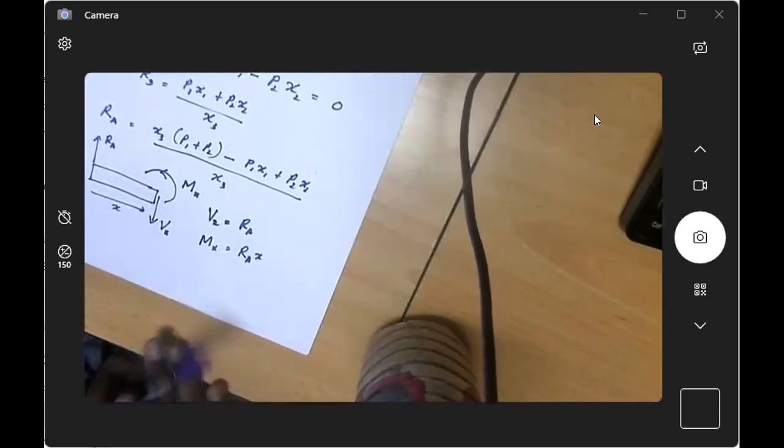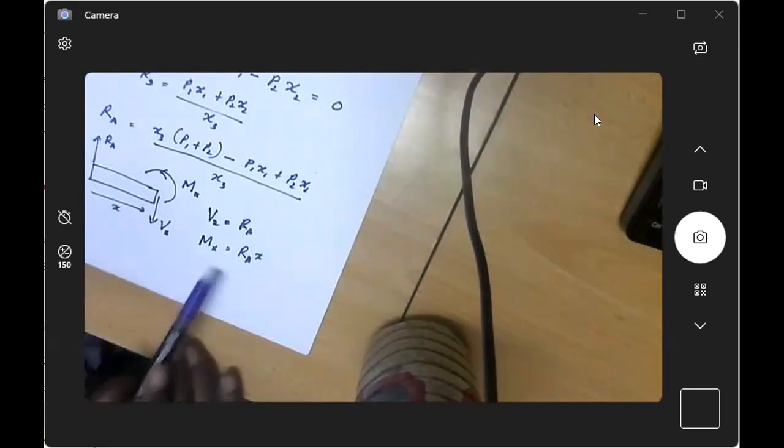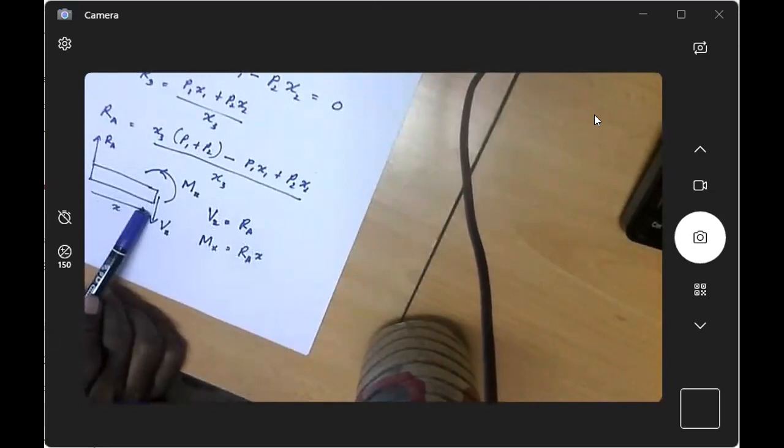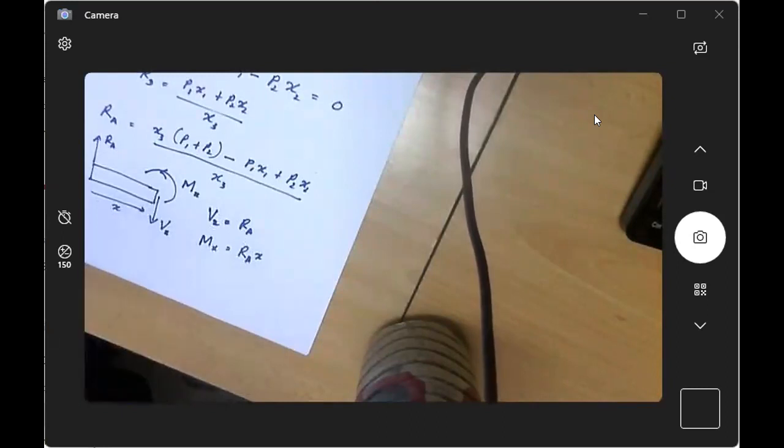This is obvious, right? When you have a long beam and when you push it at the middle, you will see it will try to sag. That happens because of this moment. Exactly, nothing else, right? So in this case, the shear force is a constant in between these two points, but that is not the case for all loading systems. So let's see what will happen if we have a slightly different loading system.